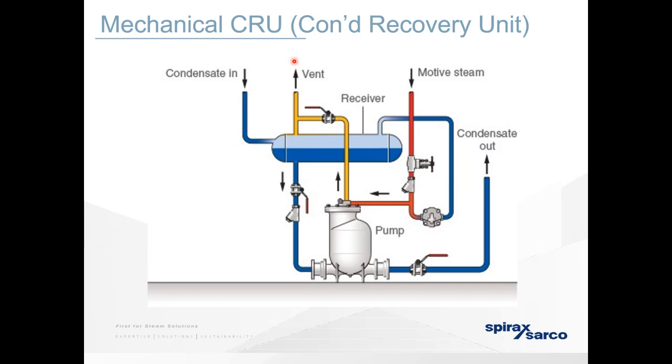Not to forget the feed water itself as well, so the raw water that you're bringing in, because that again is a calculation cost. You've had to replace water in the boiler. So I do believe he needs a steam flow meter, a condensate flow meter, and also the makeup flow meter, so they can see the difference, or at least the steam flow meter and the condensate return flow meter.